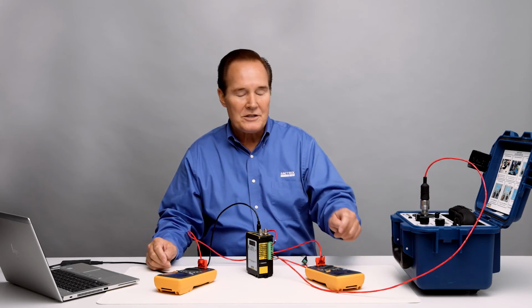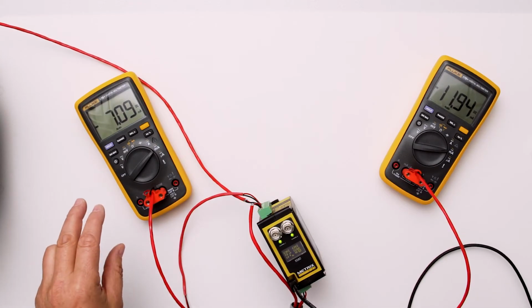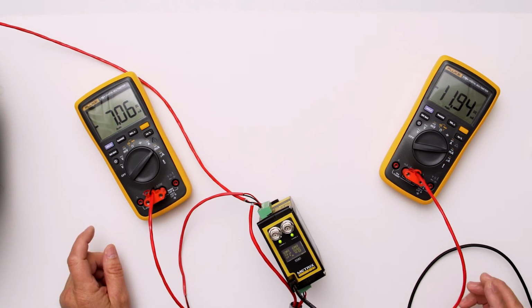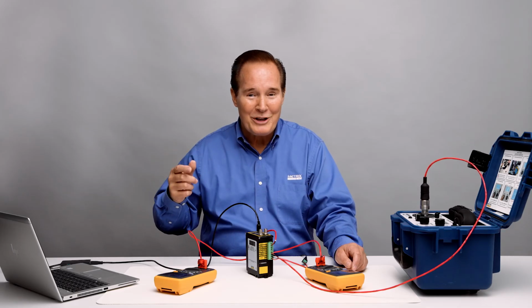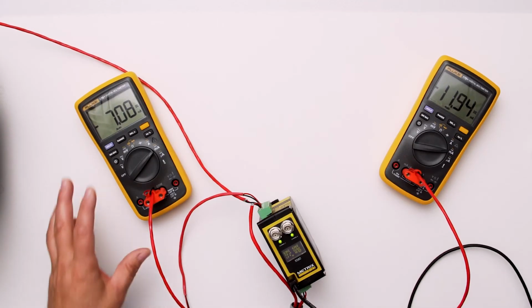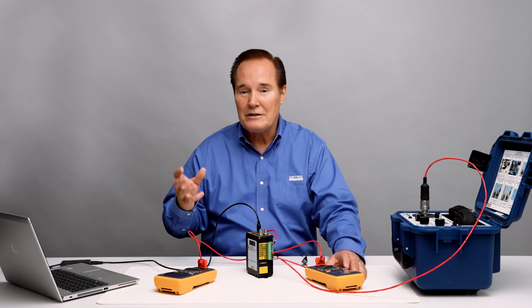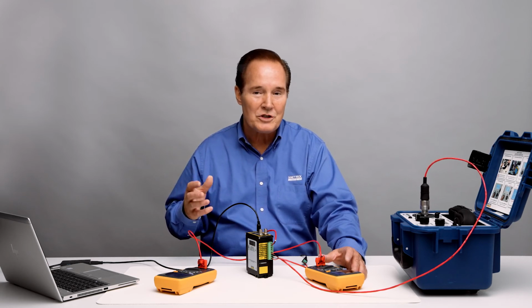And you'll see that the vibration is something less than that. So even though we have these impact events going on, the vibration level is less, and that's important. I have this set exactly at 200 millivolts, and it's 100 millivolts per G. 2 Gs is 20% of full scale, so that's 2 times 0.2 times 16 is 3.2 milliamps. Plus 4 is 7.2 milliamps, and that's what you see in this window. Typically that won't happen. You can have a mismatch between the acceleration that you're reading and the impact events you're seeing, and that's why you want an impact device, so you can actually see impacting versus just vibration.